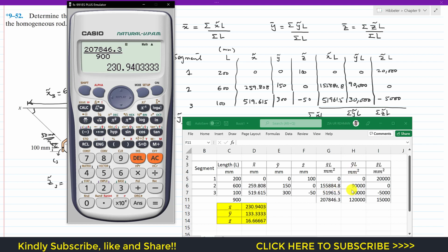Similarly, the summation of y tilde times L is 120,000, and if we divide it by 900, we get 133.33 mm. And similarly, z bar is 16.667.